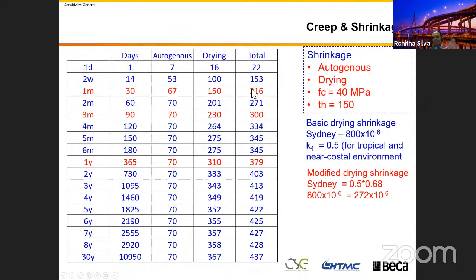You don't want to go back and do all the calculations for an exact date, saying I'm going to put the barrier on that date, the age of the bridge is 28 days, no 56 days, 3 months later. You can't dictate the construction terms to the contractor. That's not right, but you can use your general understanding to make judgments. That is quite important, and when you design and do the calcs, it helps you a lot.